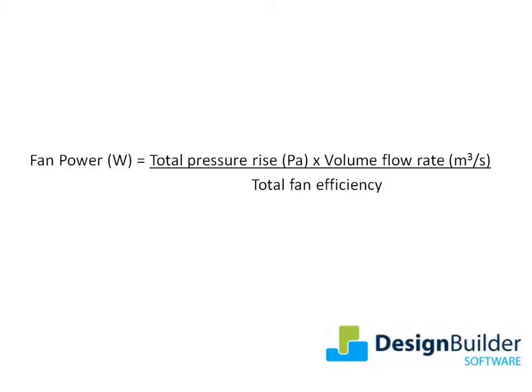fan characteristics. For example, CIBSE Guide B indicates that forward curved multi-vane fans, which are commonly found in HVAC systems, are likely to have an efficiency of 45 to 70% and be used in low to medium pressure applications, giving a maximum positive pressure somewhere between 500 and 1000 pascals. The default values are therefore a reasonable starting guide for this type of fan.